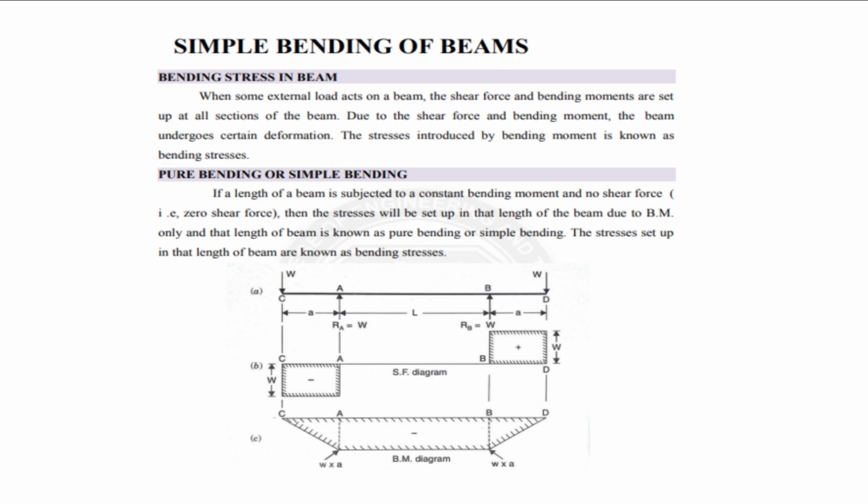So here we are going to see the topic simple bending of beams. In bending stresses in beams, when an external load acts on a beam, the shear forces and bending moments are set up at all sections of the beam. Due to the shear force and bending moment, the beam undergoes certain deformation. The stress induced by bending moment is known as bending stress.